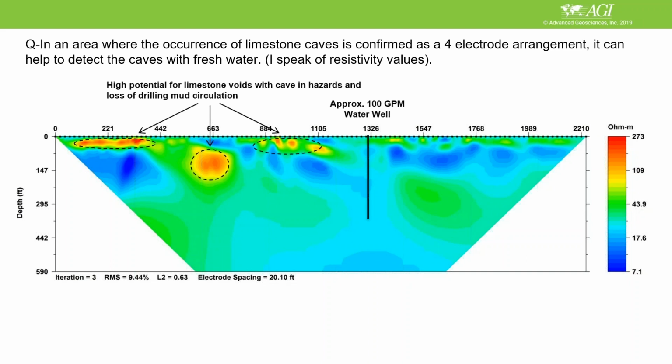In deep ocean bottom studies, towing a survey on a floating cable while going 2, 3, 4 kilometers per hour on the water surface, on a mountain doing mining investigations, or in a desert area doing geotechnical or groundwater investigations, wherever you do, the first recommendation is to go to dipole for a multi-electrode system. If you have a single channel instrument, yes, dipole is also recommended, but it will take a longer time. So you are better off timing it, and you can do that.